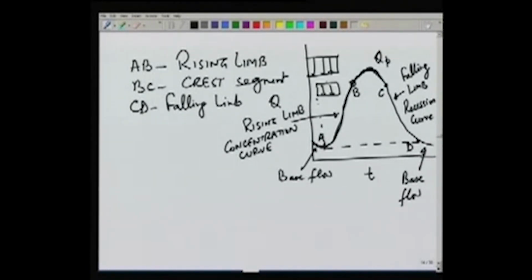So effectively the rainfall starts at the point A, because before that whatever rain has occurred is not going as runoff, it is satisfying the infiltration and evaporation requirement of the basin, and if there is some depression storage, it will satisfy the initial abstraction requirements.